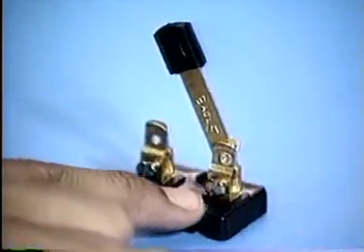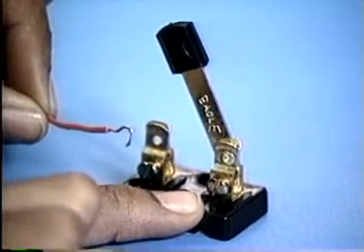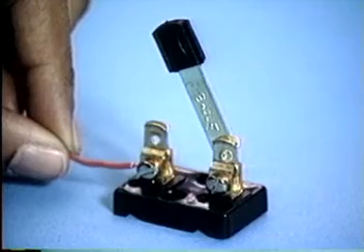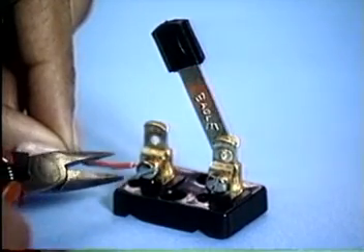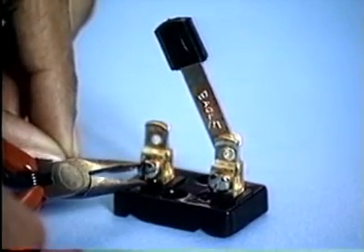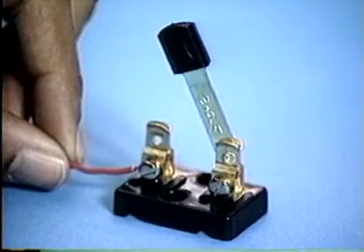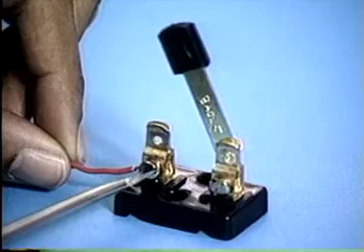In some cases, you'll have to fit the loop under or around a screw terminal. To do this, again check to be sure the loop is wrapped in a clockwise direction. Then use the long-nosed pliers to squeeze the wire together and tighten.